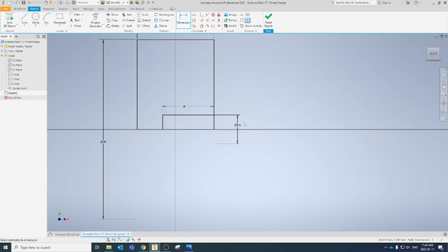And the reason I'm doing 4.5 is if I'm designing this for a 4.0 carbon fiber axle, I need a little bit of tolerance because we know that some 3D printers don't always print perfectly, and we need a little bit of space on both sides for that axle to actually fit in here. You might want to do a bigger tolerance if you're planning on using any sort of adhesive in here, because you are allowed to use any sort of adhesive that does not add volume to your design. So a super glue that dries without leaving a volume would be allowed.